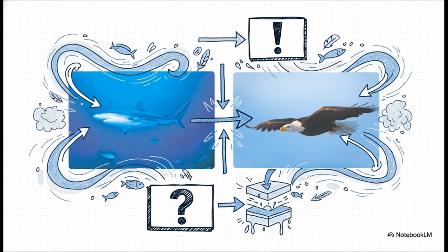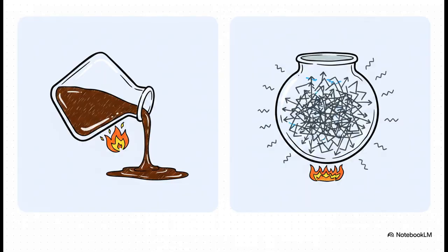Viscosity is essentially just the fluid's internal friction. Whenever a fluid moves against a solid body, or even when fluid layers just move against each other, this internal friction creates drag. Okay, this is one of my favorite bizarre physical truths. Heating up a liquid makes it flow easier, but heating up a gas actually creates more resistance. It sounds backwards, right? In liquids, molecules are bound tightly by cohesive forces. When you heat them, they get energized, break those bonds, and slide past each other easily, kind of like hot syrup pouring way faster than cold syrup out of the fridge.